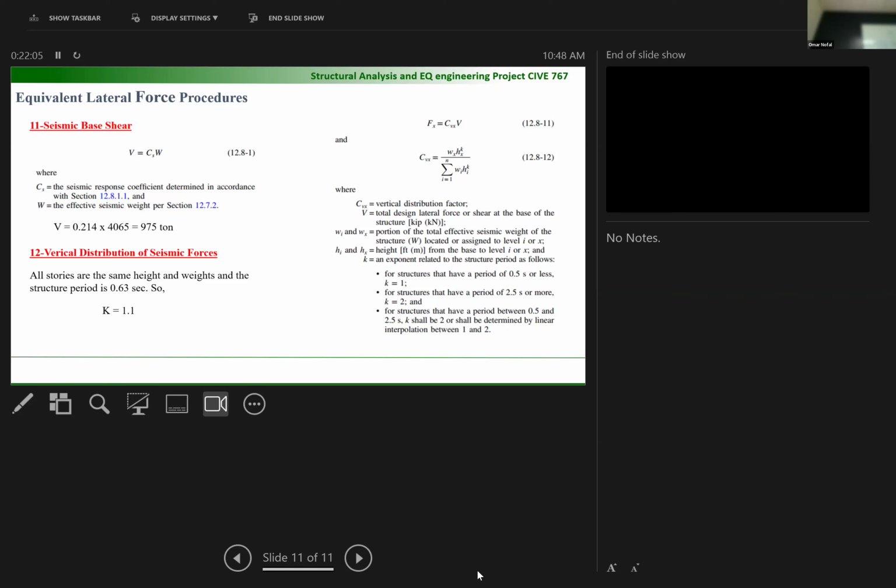And from a financial perspective, lateral load analysis, when you run your building, is not going to take much time. Since we are using diaphragms, using degrees of freedom, and increasing the mesh size of the slab, it's not like a slab system that has lots of points. What takes time in the software is the mode shapes, combining them, and solving the matrices, since you have multiple degrees of freedom, a matrix for the mass and a matrix for the stiffness. So it's more dynamic analysis rather than finite element. Right. But you're not going to integrate, so. Yeah. But you can.